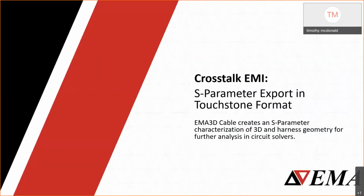Okay, let's talk about some other environments. So we've covered radiated emissions. We've talked about ESD. Let's talk about EMI crosstalk, which is a really important metric for cables. So we have a noisy signal in one cable that is routed next to another wire. The victim wire may have induced voltages from being routed next to the other cable. So having a tool that can quickly assess crosstalk is important.